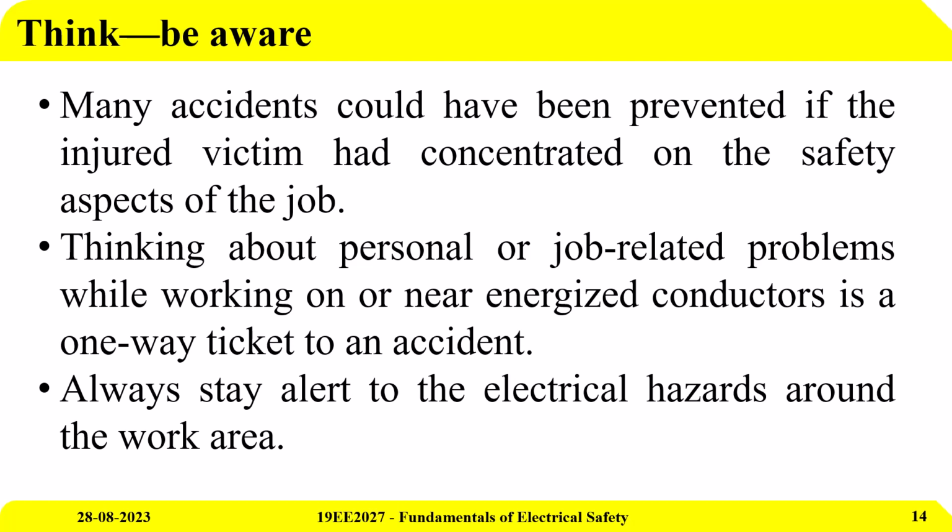You should know the previous faults which happened to the particular devices and equipment. These are the things which we can expect and predict, and you can work on it and make sure that you are on the safer side. We should be fully aware about the particular equipment before we start the work. Always stay alert to the electrical hazards around the work area. Anytime we can expect an accident because we are working in a live energized area, so we should have proper awareness on that.